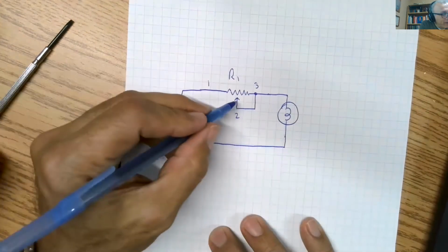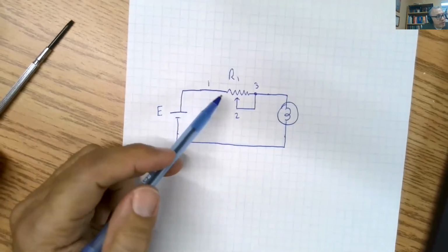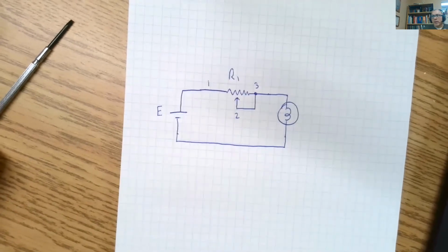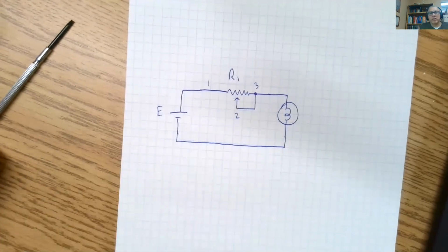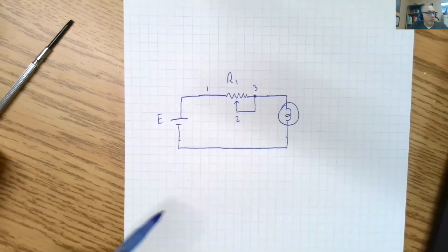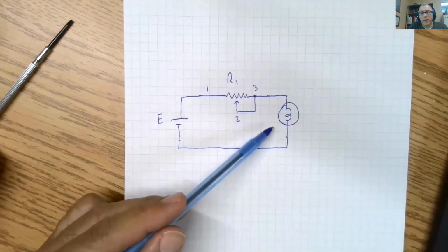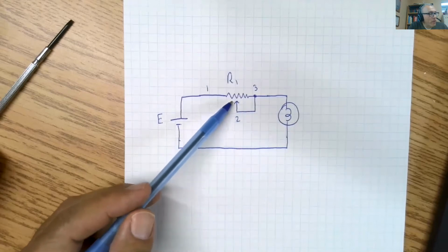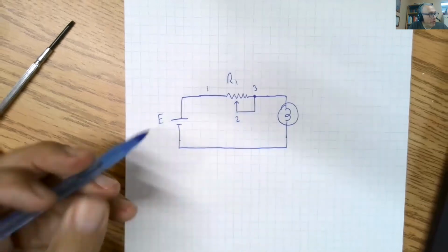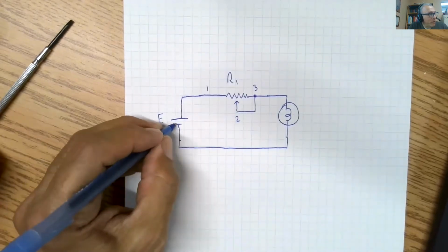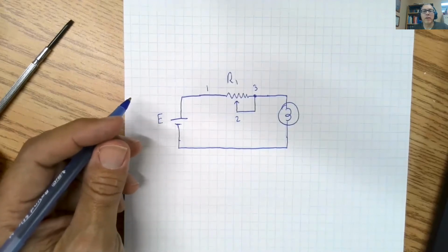So what happens here is as I adjust pin 2, the resistance between 1 and 2 is going to go from 0 to the maximum value of that variable resistor. All right. So this is now, in essence, like we could say in this case, a dimmer, but we're just using it as a current limiting device. So it's affecting the current of the circuit directly as an in-series resistor. Okay. And if we just hop to Multisim for a second.